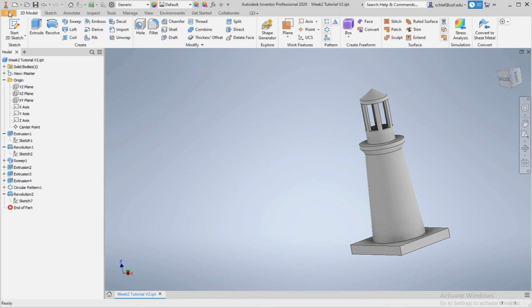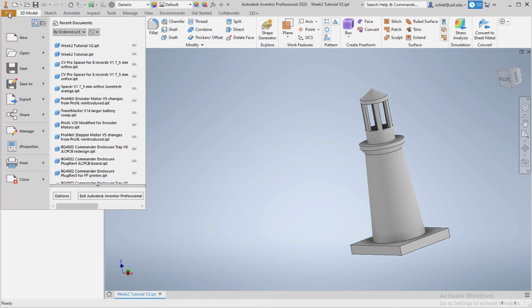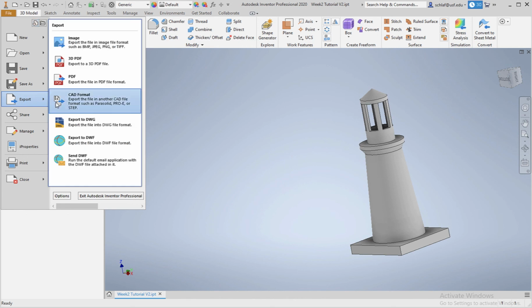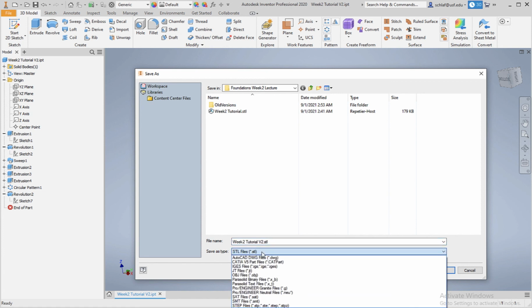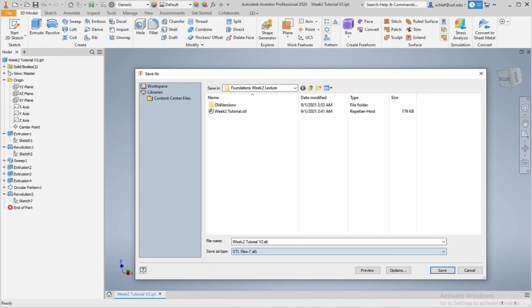So basically what you need to do there to get a printable file is to go to export and CAD format. Here it's already auto selected because I usually have it like this, but usually it comes up with a DWG file pre-selected, so you want it as an STL file, right? STL, that's what the slicer for the 3D printer can understand.